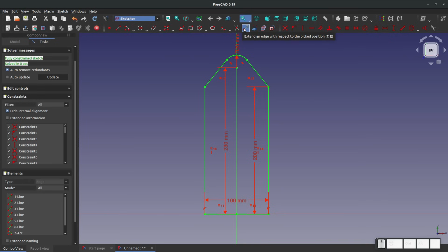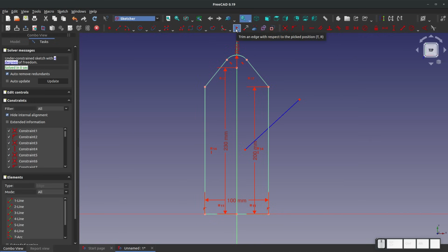This is for trimming an edge and extending an edge. That's a little bit more advanced, and I don't think we have to go through that here. Oh, maybe I'll do the trim, the edge trim. So let's say I've got intersecting lines. I simply choose trimming an edge. From the point of intersection, if I click this side, it gets rid of that line that I trim, right? So it can be useful. It also adds a coincident relation at the point of intersection.